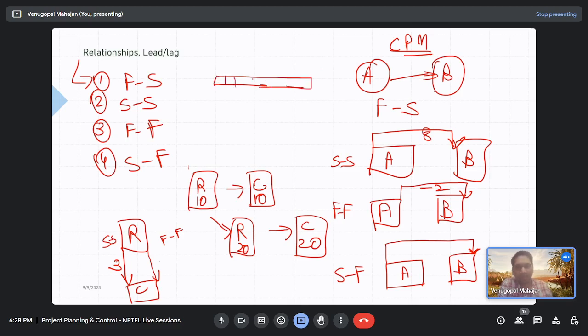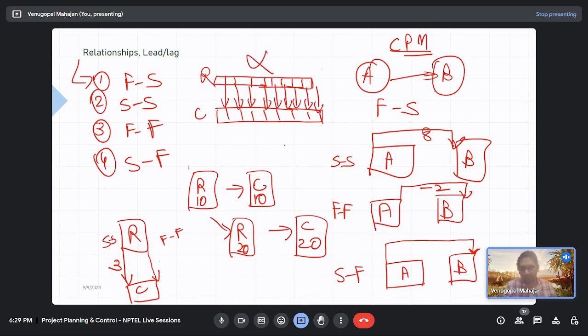So this reinforcement activity could be 20 beams like this, and this concreting activity could be 20 beams like these, and you could have a continuous relationship. Still we are not discussing this. We are just breaking it down into endpoints and working on it. This kind of relationship you can deal with the beeline diagramming method, which is above the contents of this course, but you can find it in a scheduling techniques course.